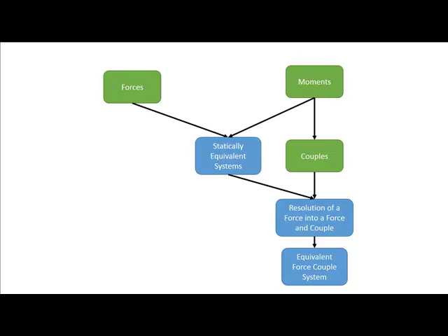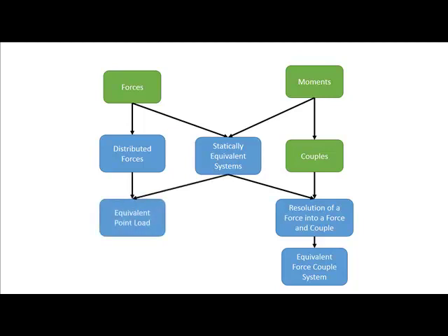And so using this process, we can simplify more complex systems into very simple systems that consist of one force and one couple. All right, so also for statically equivalent systems, we're going to use this with distributed forces. So forces, we can break down into point forces and distributed forces. And for distributed forces, adding things up that involve calculus is very difficult. Generally in statics, we convert distributed forces into their equivalent point load.